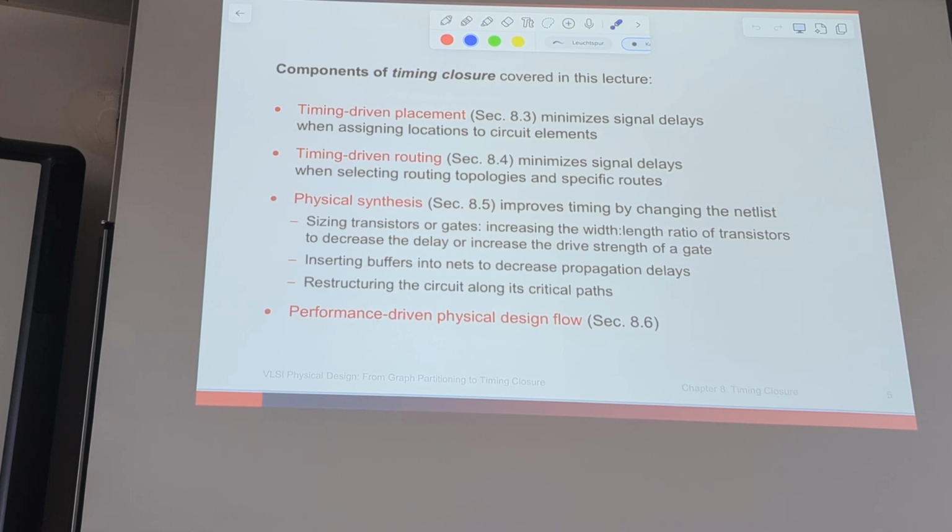So which paths or which routes can be very long because they are not timing critical, which wires need a very short path, which cells have to be close together so that you achieve a short delay. This can only be derived from the circuit and your timing requirements.